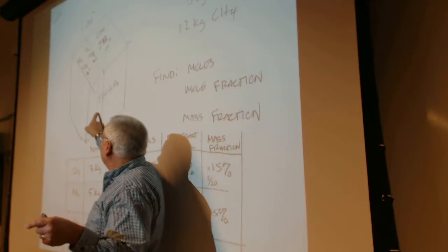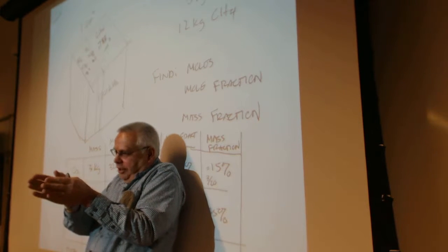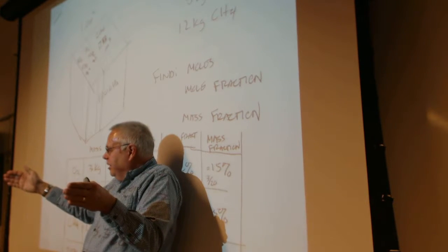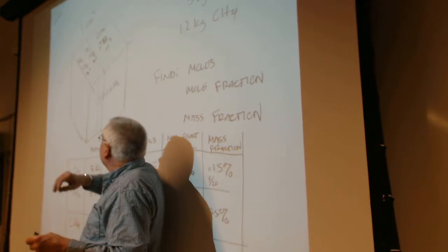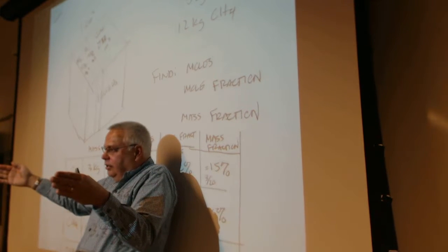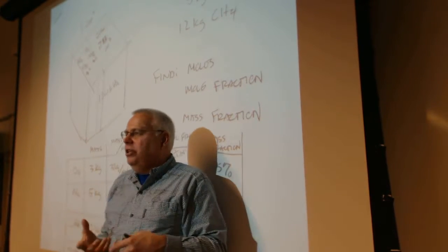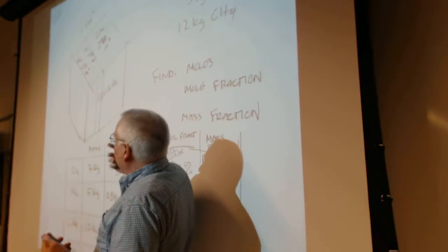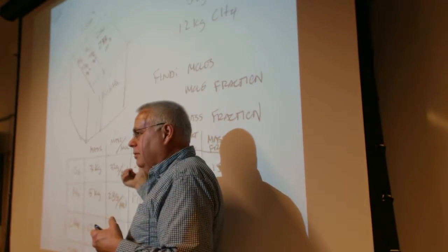And likewise, if I do that for these other ones, the nitrogen, pull it out, it was 17% at 100 kilopascals. Now it's going to be at 17 kilopascals if it's in 1 cubic meter. And if I take this one, it was 9%, and it was sliced and expanded out, it's going to be 9 kilopascals. And that's the way gases act. That's the way the moisture in the air acts. The partial pressure is proportional to the number of moles in the air.